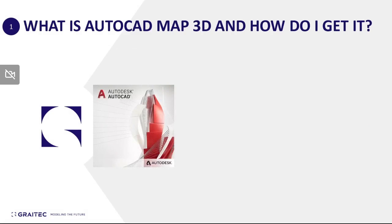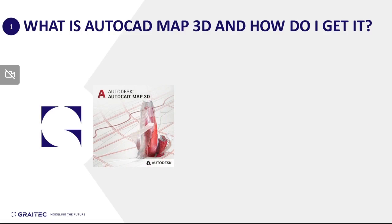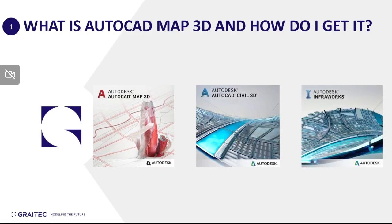Now, these tools that I'm about to show you are not available in vanilla AutoCAD, so make sure you do download Map 3D. But if you are a Civil 3D user, these tools are also in Civil 3D. To see them in the ribbon, you just change the workspace to Planning and Analysis. If you're using InfoWorks, all the FDO tools, Feature Data Object tools, are in there. So you can connect to the same data, you can view it there, but if you want to manipulate the data, which is what I'm going to be doing, then you'll need to use Map 3D or Civil 3D.